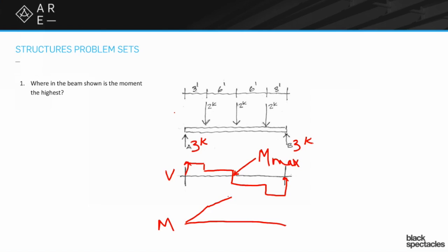So you're just separating those out into different boxes. So the first one was the 3 kip amount by the first 3 feet, and then you jump to the next box, which was 6 feet long, but only 1 kip high. Right. And so you're just adding it up as you go along. Yep. And then because we crossed the 0 line, these are all negative, so we're basically going to come down those same numbers. So you're going to come down a total of 6 to the +9, and then you're going to come down the rest of the way down to 0.